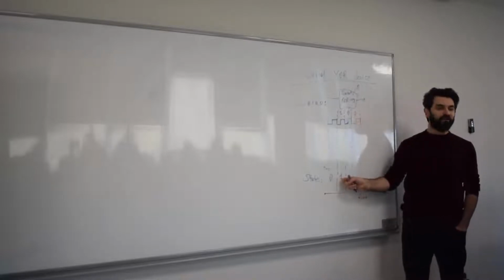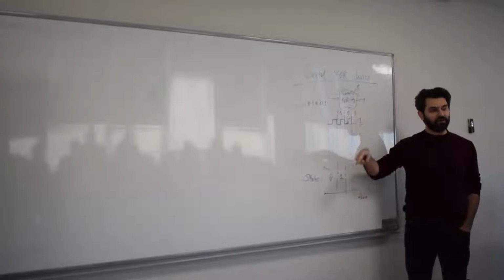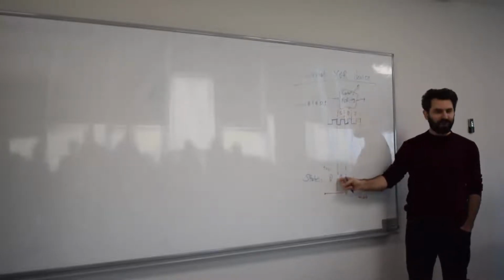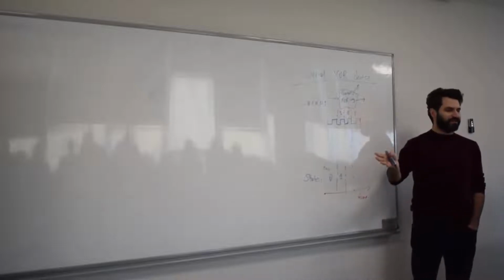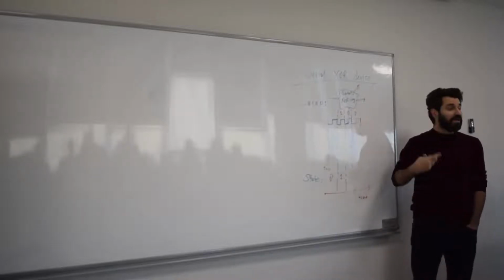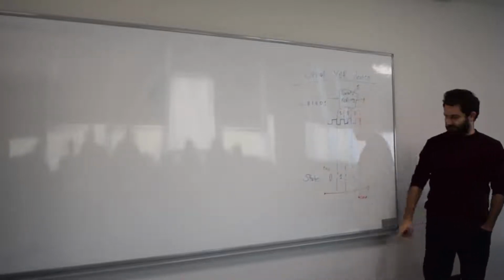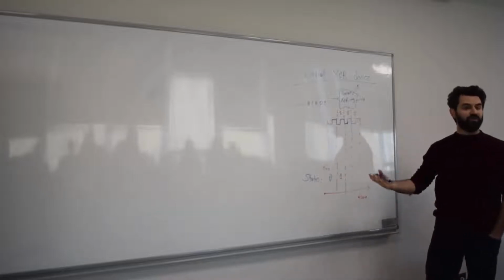And that new state is also the output. Do you remember what type of machine that is? Is this Mealy or Moore? In other words, the state becomes your output. It's Moore, right? You don't need to process that information with extra gates anymore, because that's your state as well as your output. In other words, the XORing output. So this is your new state and your output. That makes it a Moore machine.